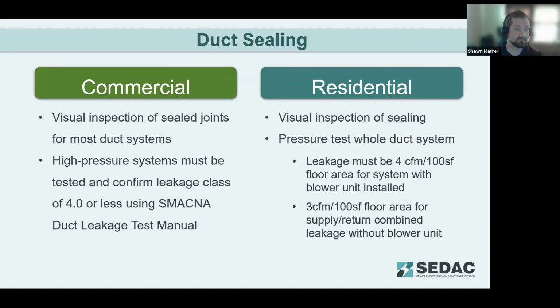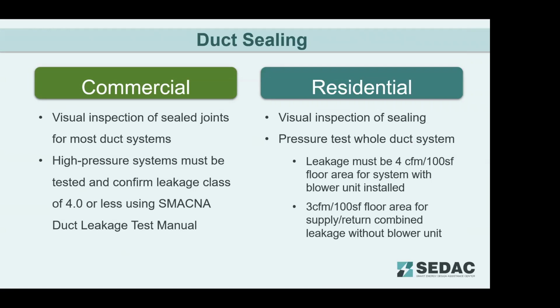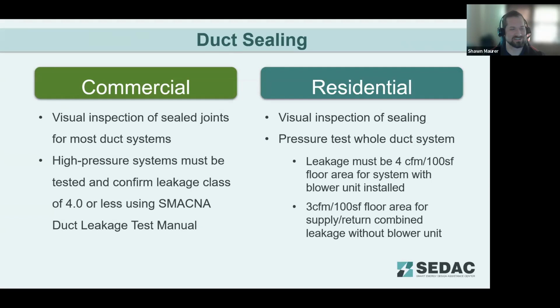For duct sealing on the commercial side, again, if you've got that high pressure duct system, it needs to be tested per SMACNA, the Sheet Metal and Air Conditioning Contractors' National Association. It's hard to remember because it's such a long acronym. But they have a duct leakage test manual that specifies the testing procedures.